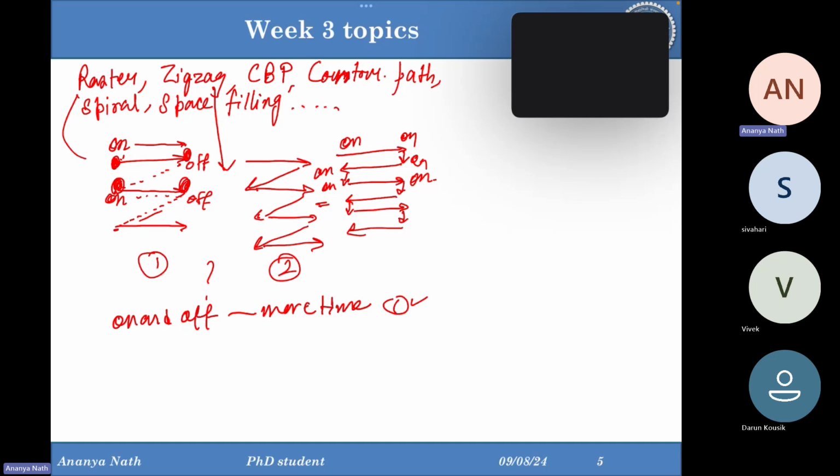It depends how you are turning off the material with the scanning. So in most of the cases, this is the path to be printed. You have turned on here, you have moved to here, and at the particular point you have turned off. So basically here will be lesser material than usual, and here more material than usual will be printed. And because of which the accuracy will be disrupted. So this is again one thing, because of the inertia. Okay, so more time will be taken.